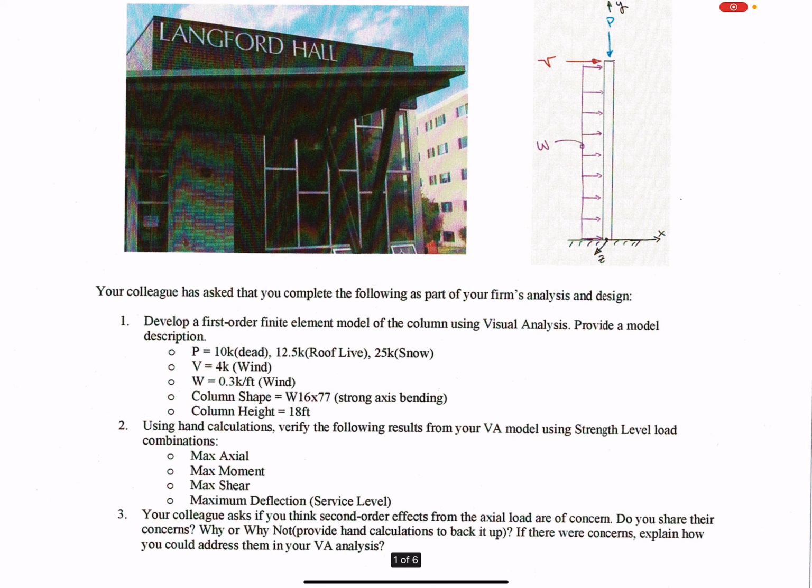Service level. What does it mean to be service level? It's not factored. When you say not factored, what does that mean for something like earthquake or wind? Factored. You can tell that's not necessarily the best way to describe it. What we want is a load which we are actually expecting to see in a design level event.